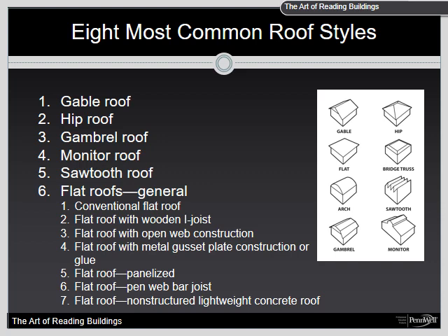2. The glue used to form OSB and also used for webs can degrade with convection heat. The glue is hydrated, and once the moisture is steamed off, the glue turns to dust. Third, a common practice is to run heating and air conditioning ducts of various size through the web. This practice removes a significant portion of the stem and gives fire horizontal access to adjacent I-beams, enhancing the extension and weakness of the exposed material.